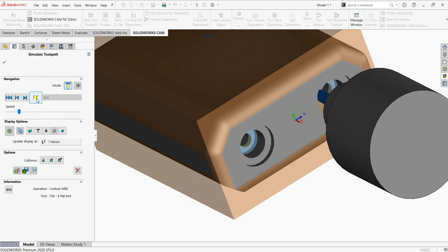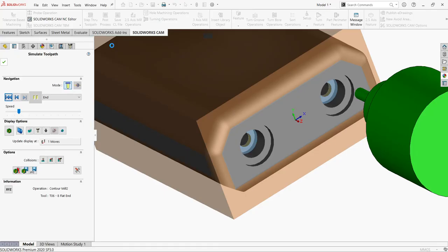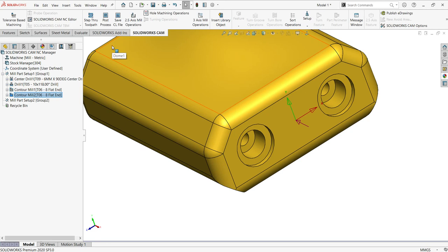Now my requirement is whatever drilling operations I have operated here, these should be copied, and I just wanted to use these operations on that side. For that, I need to generate the operation plan. It's already generated here, and you need to save it as a strategy. And for that side, to define the operations, you need to select the strategy, that is whatever operations you have created, and paste it over there. Let me show you how it works.